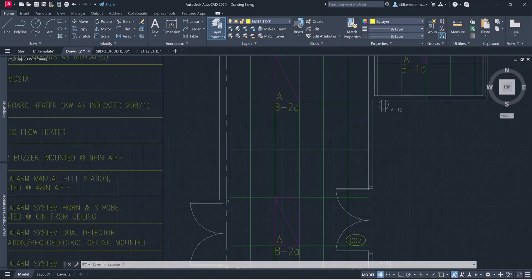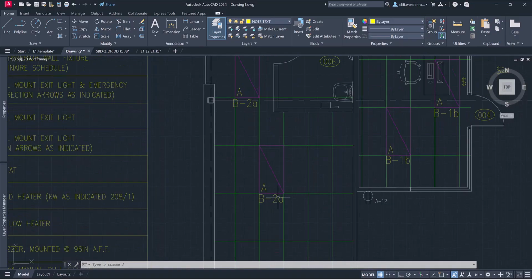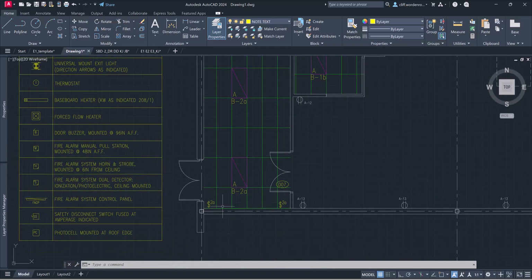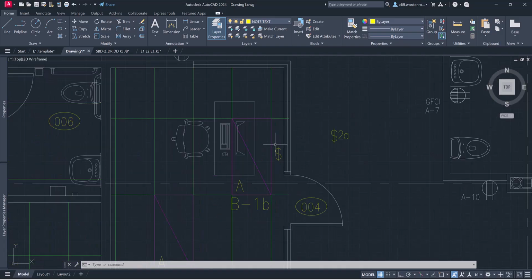So you need to make sure that there's an underscore, which is really the only non-capitalized letter you have on your drawing, here. And it's okay that all the lamps in the room are controlled by one set of switches. In a room where you just have one single light switch, you're going to have a single money sign, and then the number after it, which in this case can just be a single letter. In this case, I have B-1B. So I'm going to edit that to a B.